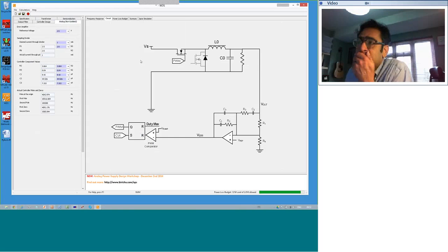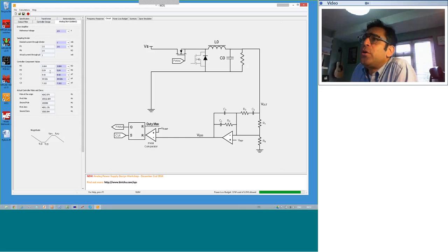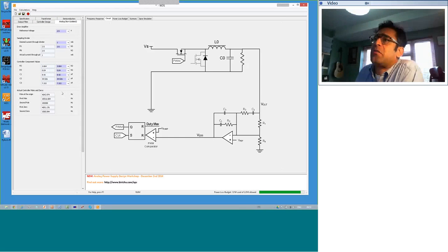Now then, these are the actual values that WDS has calculated, but these are based on these perfect poles and zeros. Unfortunately, though, you cannot buy a 3.864 kilo ohm resistor. So what WDS does is give you the nearest preferred values, one above and one below, based on the E96 series.